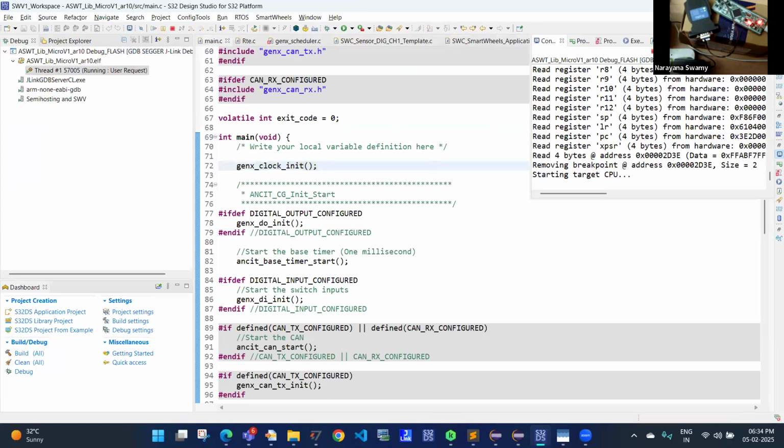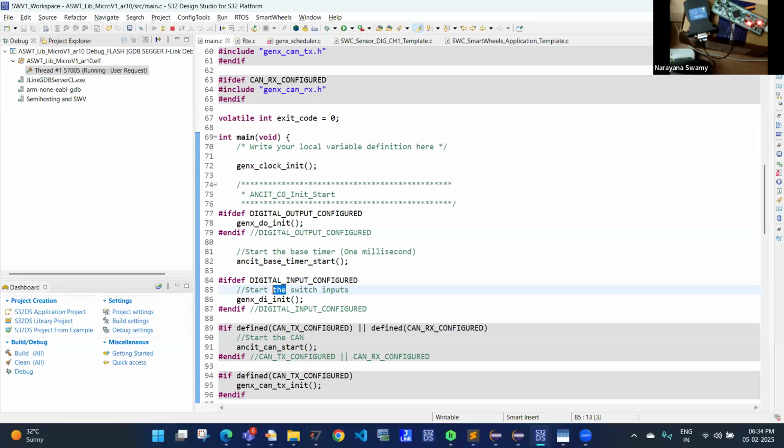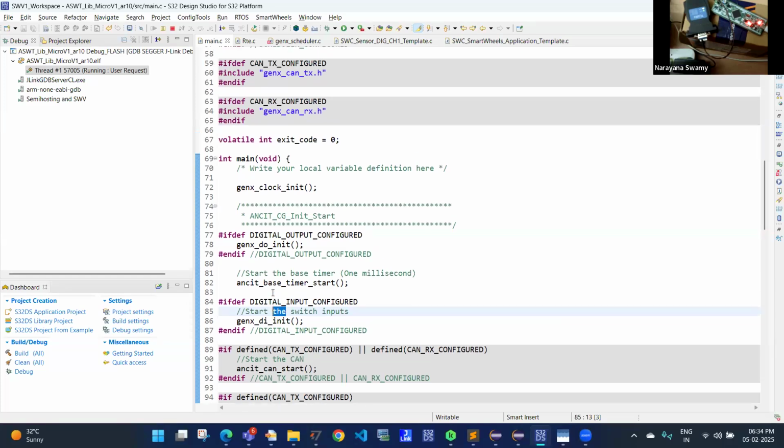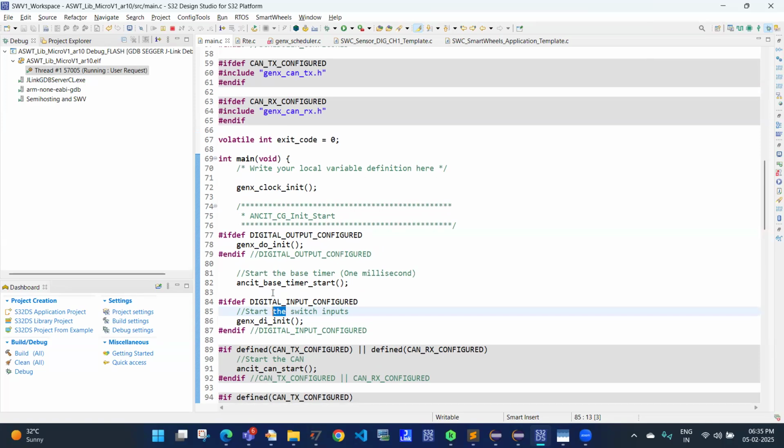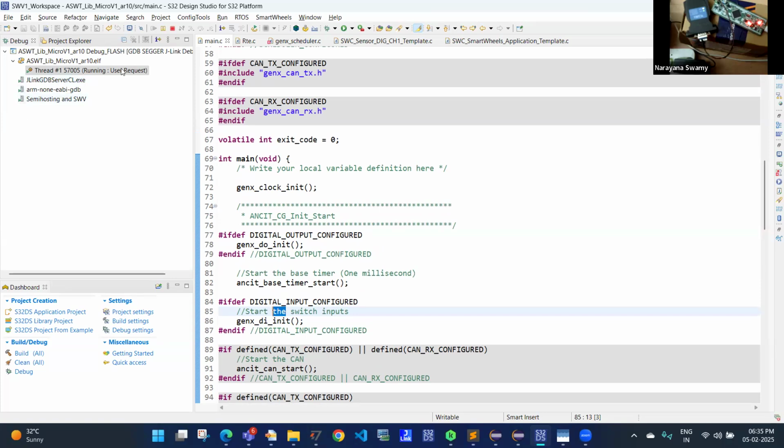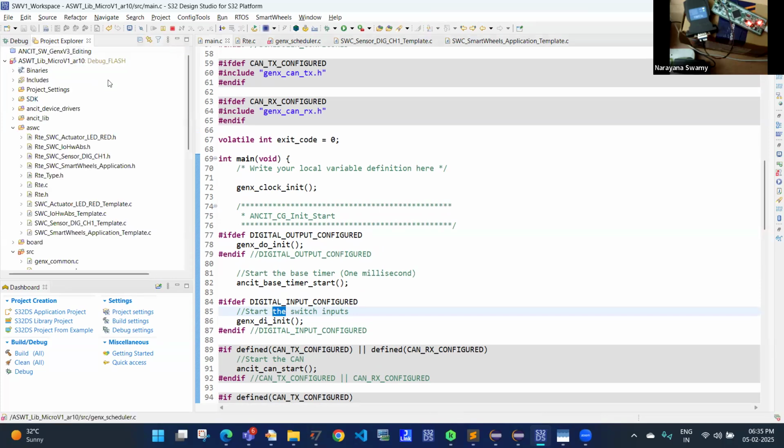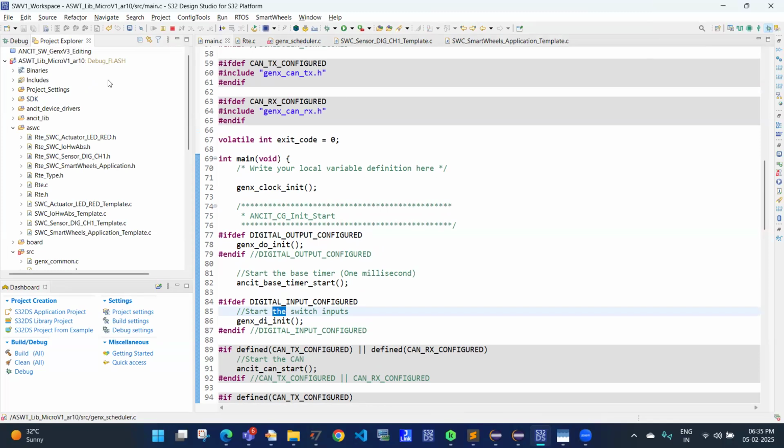So if I run this and press the button, you can see the LED glowing. Finally, in AUTOSAR. Yeah. To make an LED glow with a switch in AUTOSAR, trust me, is a 1-month project if you don't know how to configure it. Do you agree with me, people who have worked? If you're doing it from scratch, you have to properly configure the entire MCAL. Port, DIO, everything has to be properly configured. Otherwise, nothing will work. Yeah, it will take more time, sir. It will not even compile.